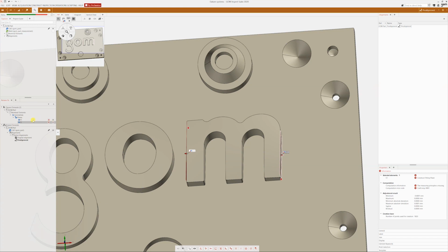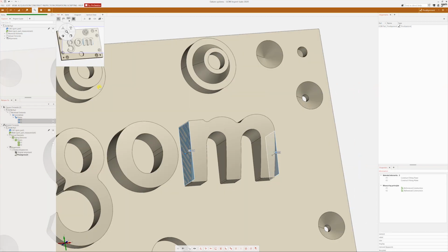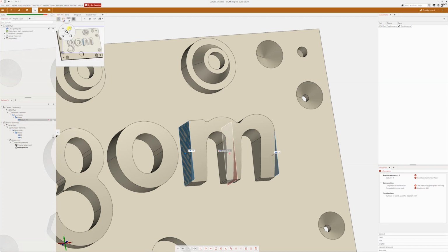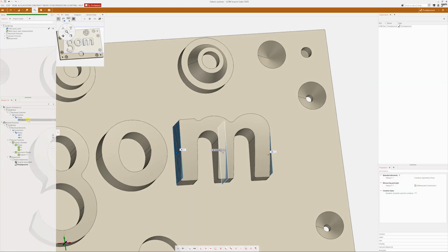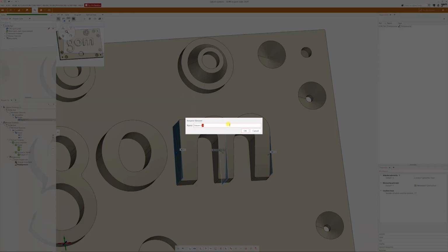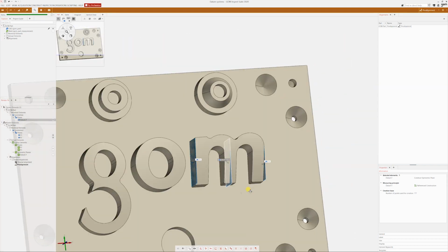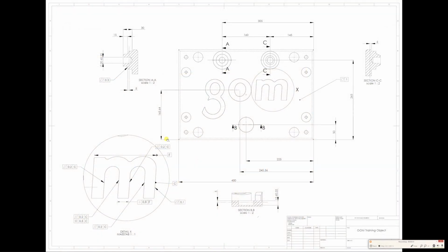Okay, we check them both, set the measuring principle to reference construction, and now we can construct a symmetric plane from these two, F1, F2. Create, and again measuring principle, reference construction, and we can rename this to datum F. And now we have datum F. So this is the way we can make a symmetry plane datum. Now that we have datum F, we can evaluate this symmetry. Let's see how we can do this.